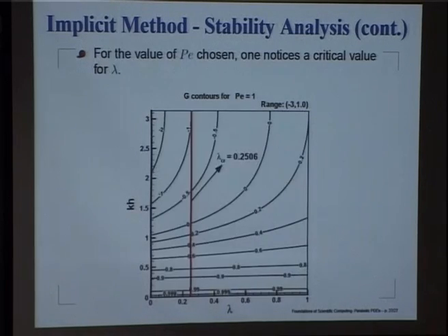And what happens if you take a much larger value of Peclet number, that is of the order of 1, and then what you notice is that finally you started seeing instability. So, now the range has gone from -3 to +1. So, what I have done here, I have drawn that -1 line here, to the left of which this region is your unstable region.